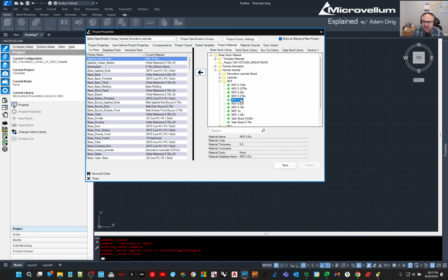Likewise, if you get a bunk of material and say everything's supposed to be 3/4 of an inch, but then when you mic it before you get cut on the CNC machine, it's 0.7435. I can go in and make the change here and then process for the CNC machine, and it's going to make the updates for all the cabinet sizes accordingly. Other cool thing with the material that I used to use quite a bit is you can specify in a material code what bit it cuts with.